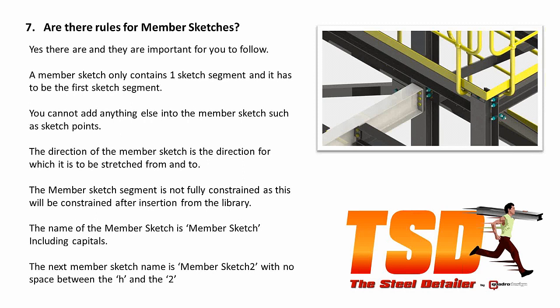That way your detailing and your dimensions and everything are not going to get thrown out of whack if you actually change it. Which is a problem that you get with relative views on multi-body parts for detailing, which we avoid. All of our member sketches inside of our sections are either horizontal or vertical. So just consider that when you do your own member sketches, that's what they are.